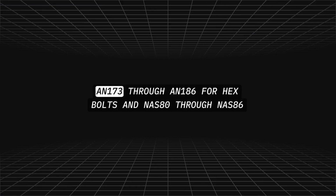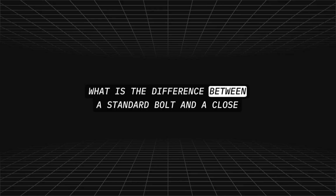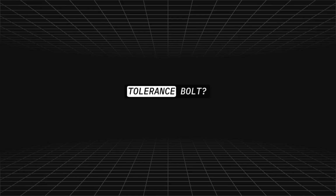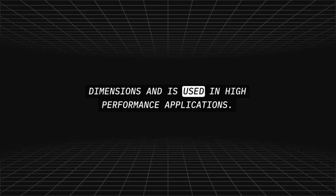AN 173 through AN 186 for hex bolts, and NAS 80 through NAS 86 for countersunk. What is the difference between a standard bolt and a close tolerance bolt? A close tolerance bolt is machined to more precise dimensions and is used in high performance applications.